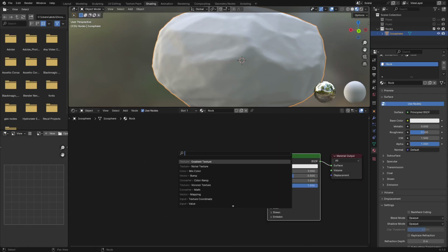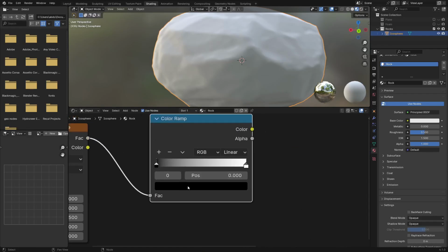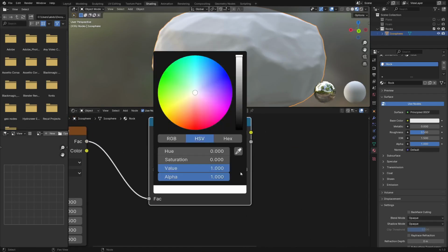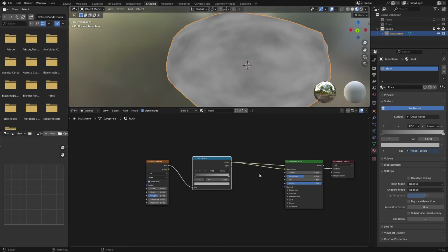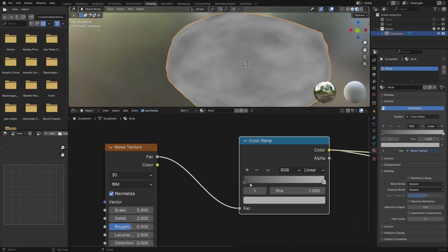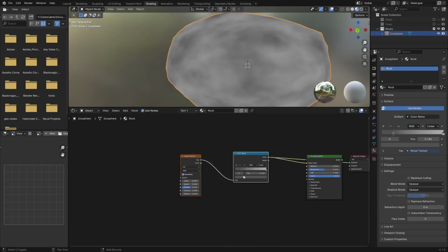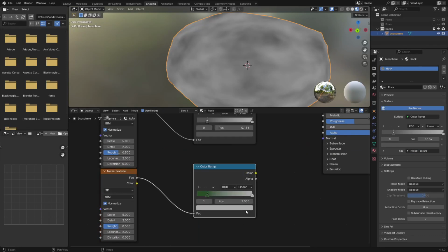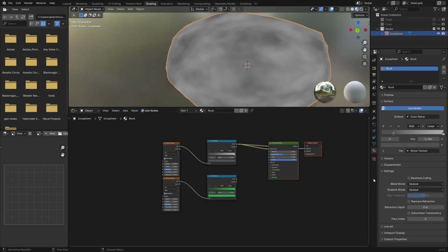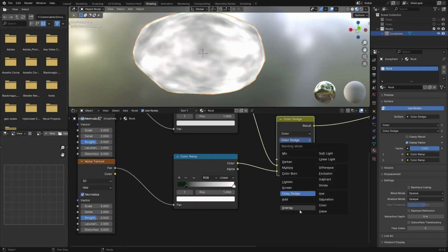Okay, now I'm going to add a noise texture, and the color ramp. Plug that into here, and then select the rock material or the rock colors and plug them into here. We can visualize that and see. Yep, this is it. Just play with that thing until you see something cooler. We can duplicate that and take some mossy colors here and there, and multiply that over that. See that fully white, and let's overlay that.